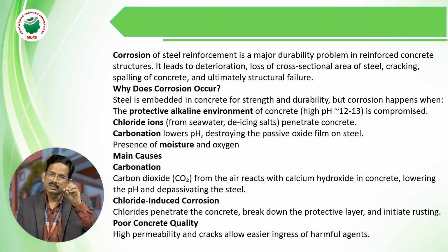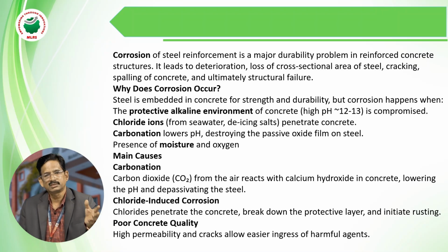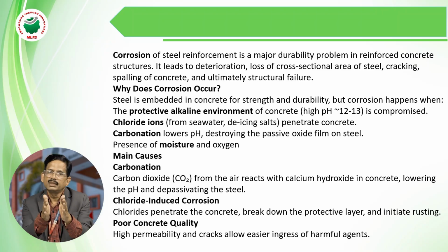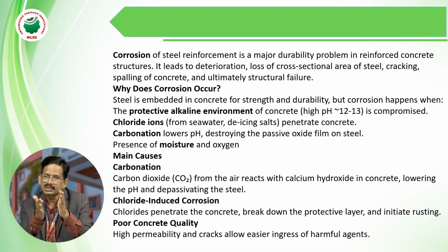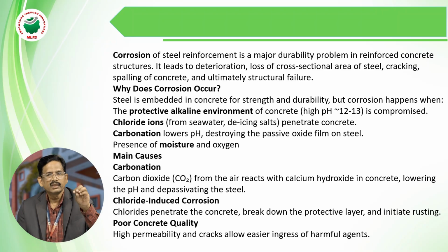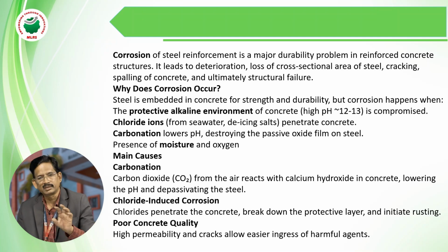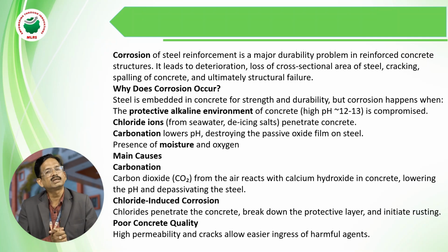The steel has a yield strength, and the concrete has a compressive strength. That's why, for designing any structure, first we have to decide the grade of the concrete, whether it is M20, M25, M30 or M35. At the same time, we decide the grade of the steel, whether it is Fe 250, 415, 500, 550 or 600. That is the yield strength of the steel.